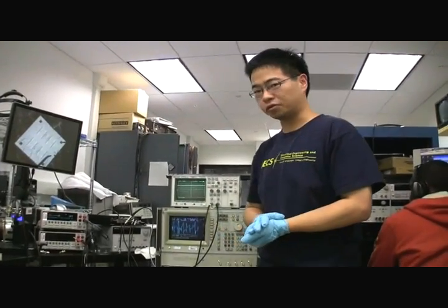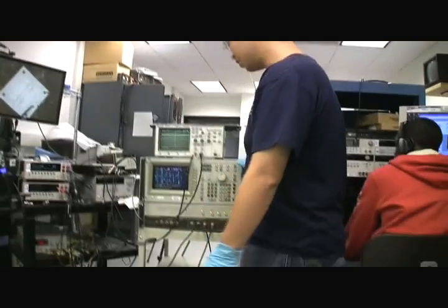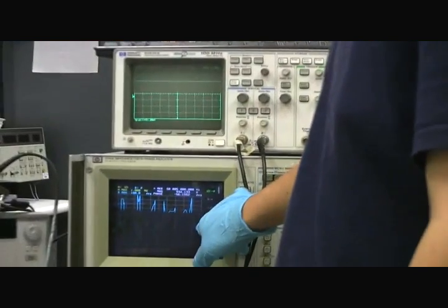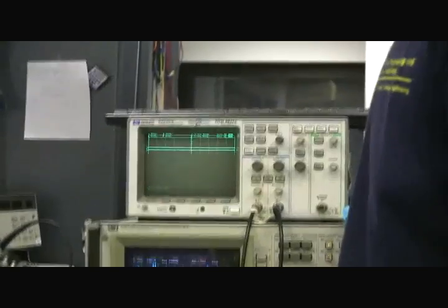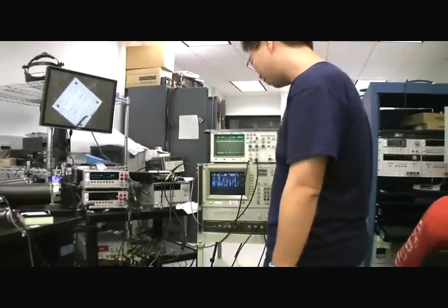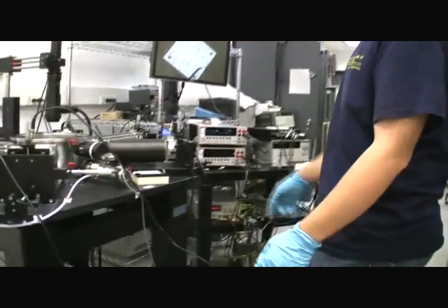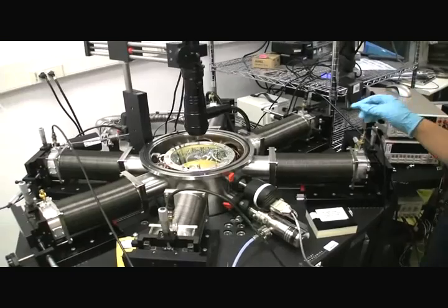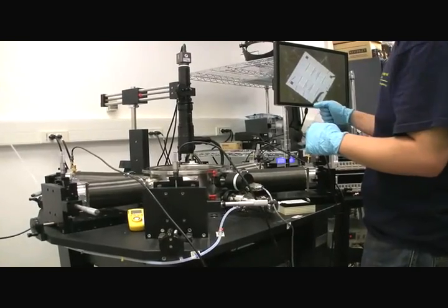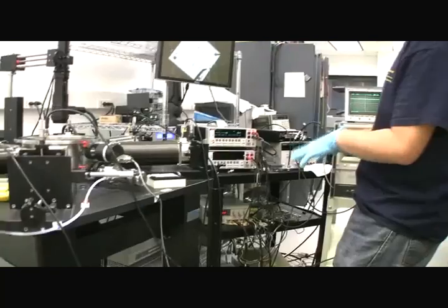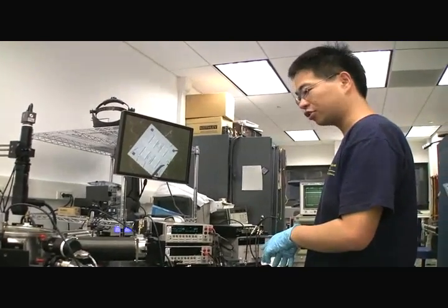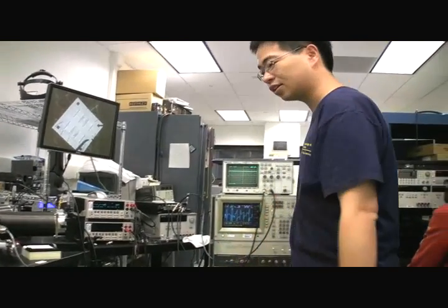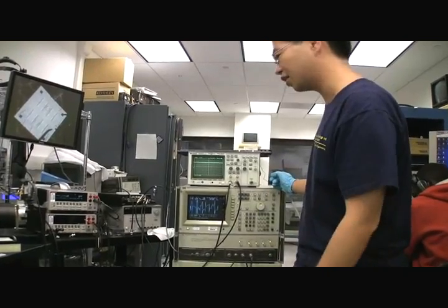So this is the equipment we use to test the gyroscope. This is the gain phase analyzer, and this is the plot of gain phase, which can be used to characterize the gyroscope. There is a signal output from here, and this is the vacuum station. The gyroscope is put into this chamber. The signal output goes through this cable and reaches that board, which converts the change of the capacitance to voltage, and goes back to the gain phase analyzer so that we can compare the input signal and the output signal.